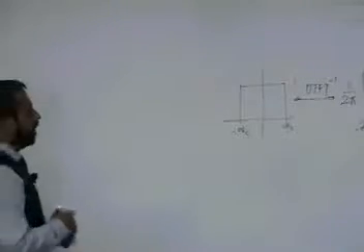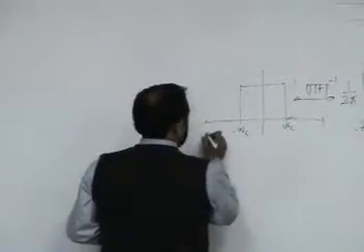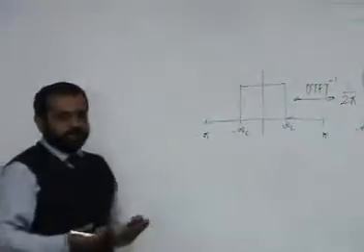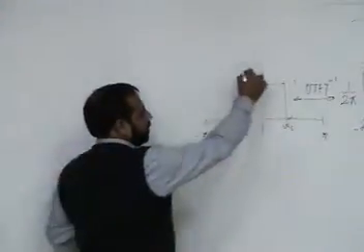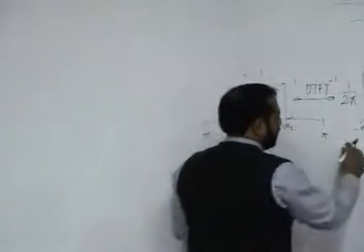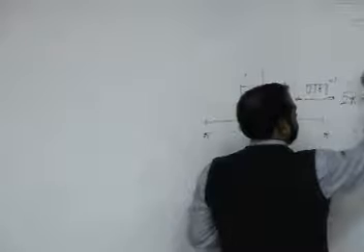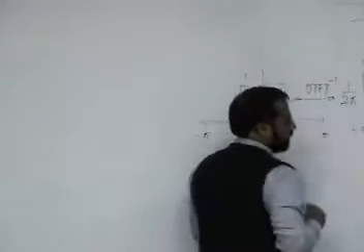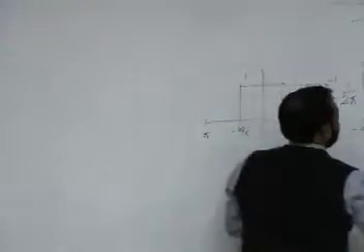So I know this is running from minus pi to pi, but H is 1 only from minus omega c to omega c. So I can easily change the limits. I say not from minus pi to pi, rather it is minus omega c to omega c, and H exponential j omega in this region is 1.